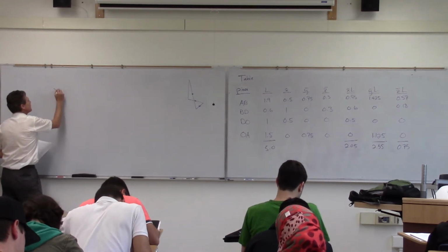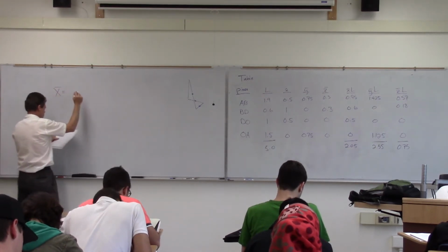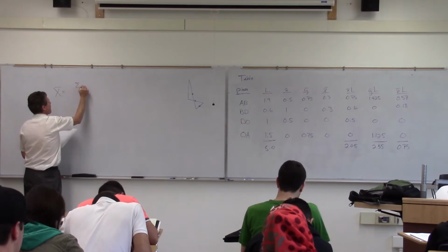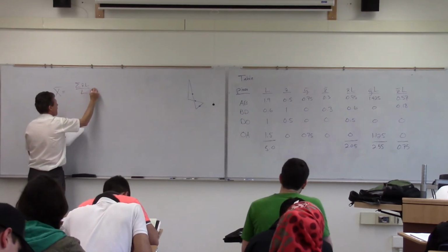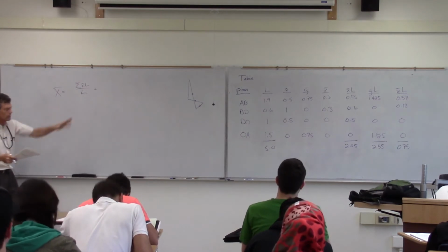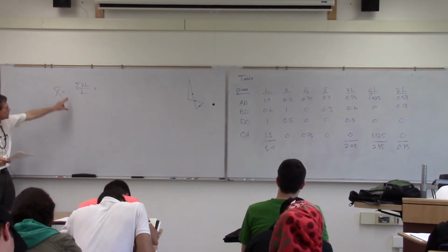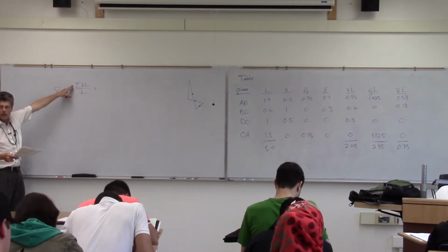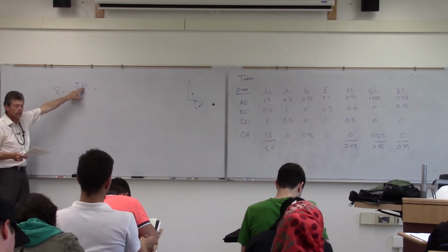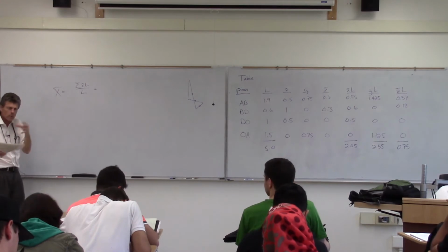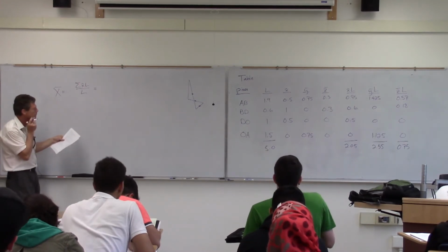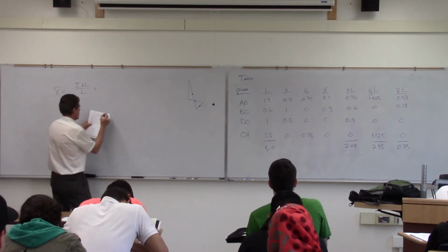And then in terms of finding the combination of the whole system then, is just simply the summation of those columns there. So it's going to be that piece there with the local discrete pieces of their lengths times their moment arms, that basically first moment of area when we think about it in terms of our equivalent system there.